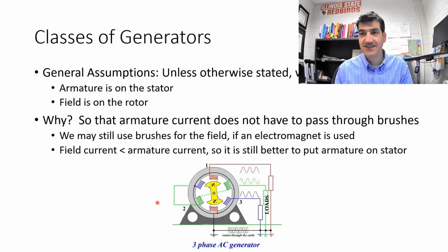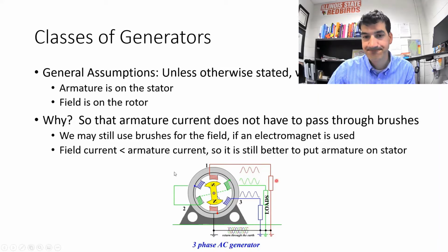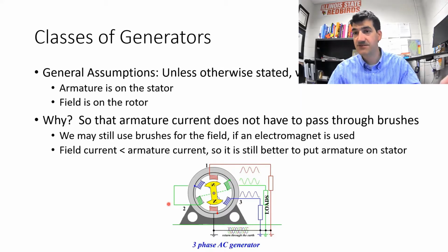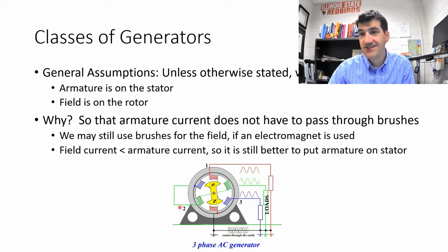However, I did say this in a previous class, there is a problem with this. And the problem is how you're going to run an automatic voltage regulator, an AVR, like we talked about last time. There isn't a way, because you can't vary the magnetic field here. It's a permanent magnet. You can't change the magnetic field of a permanent magnet as you're operating the machine.